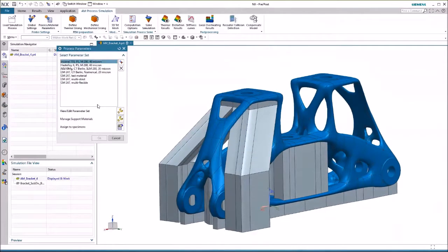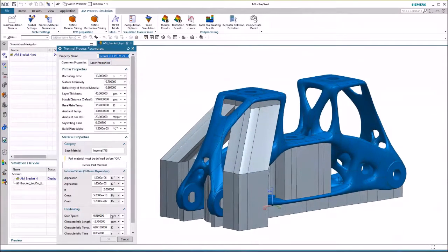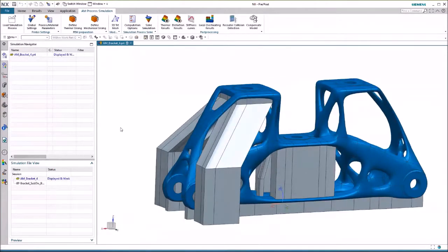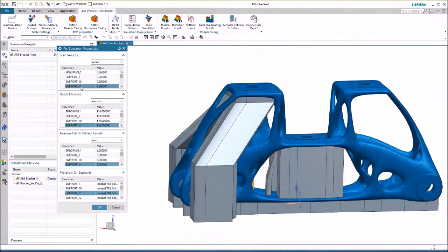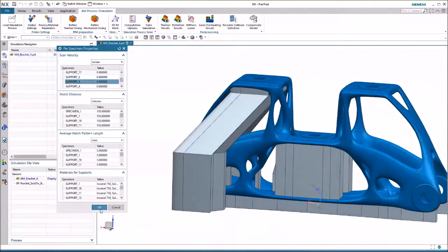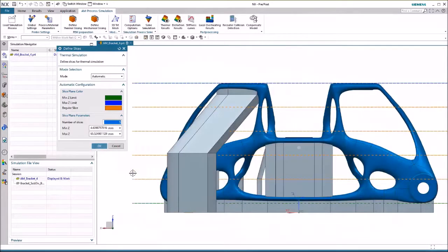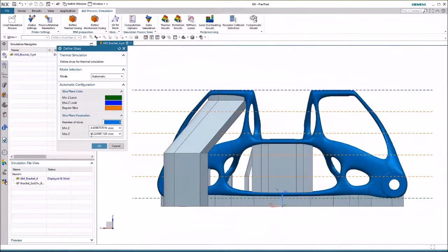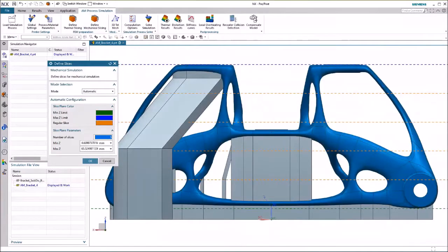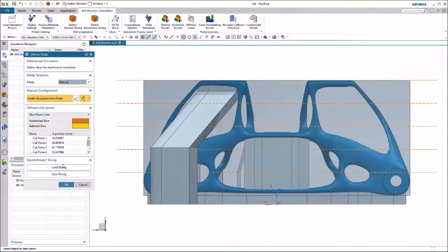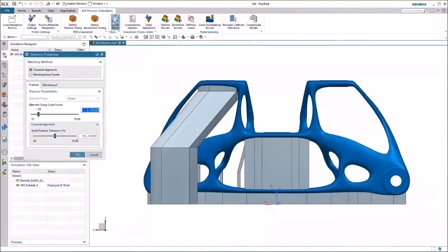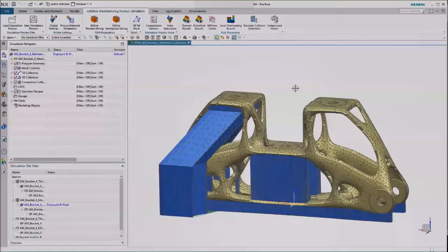You see here the definition of all material and printing parameters on your part. These are automatically applied to the supports and to the specimen itself that is going to be printed. Afterwards, you will have to create a macro slicing approach or strategy. It depends on the topology of your structure, how fine this is to be defined, but normally for a mechanical analysis, you have slices that are about 1 to 3 millimeters. In this example, these slices are a little larger for the solver to go a little faster.